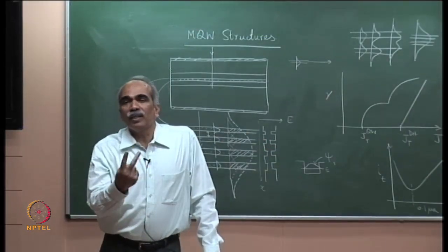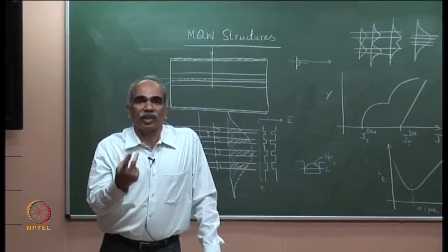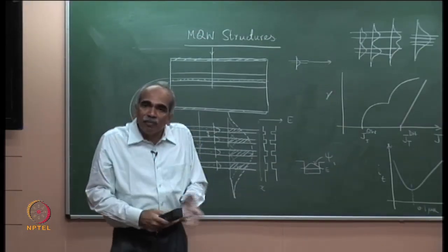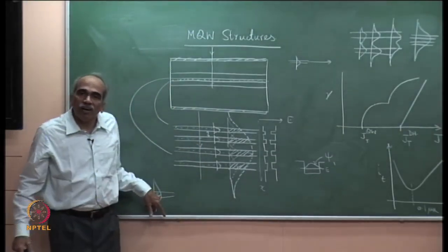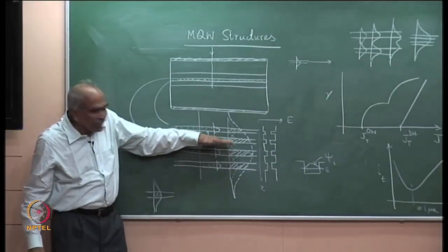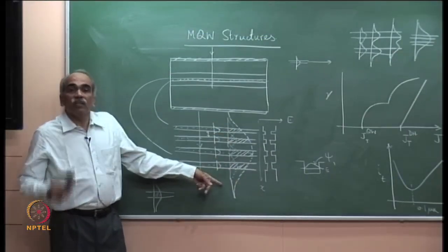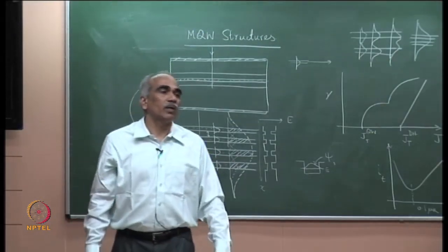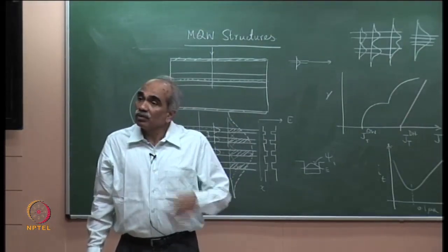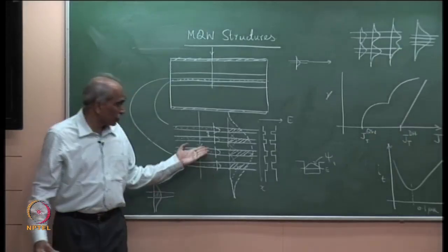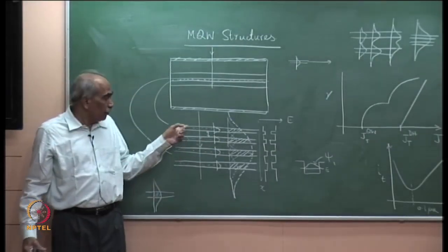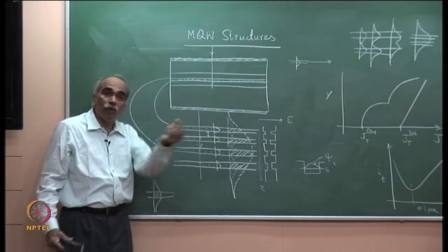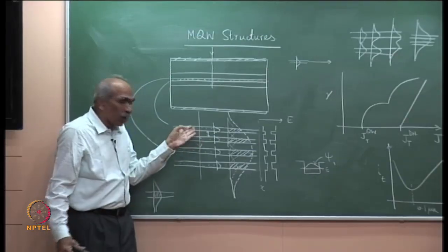So, two advantages of an MQW structure: one, enhancement of effective gamma by having one single optical field, and two, to achieve higher optical power outputs, because the overall active area is now much more. If you had only one well, the active volume of the semiconductor is very, very small.